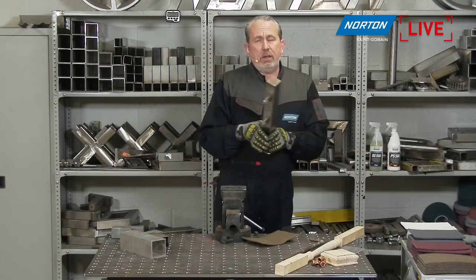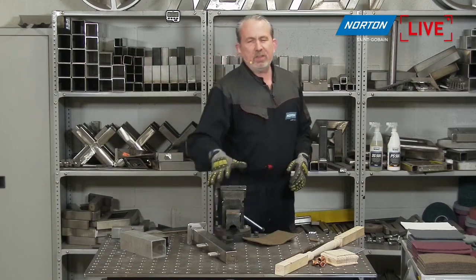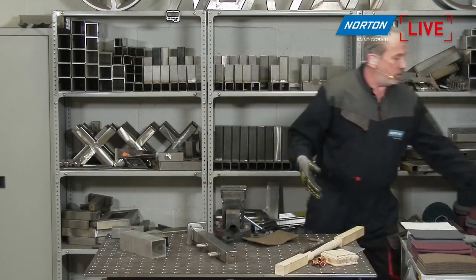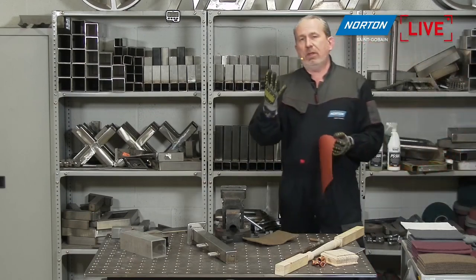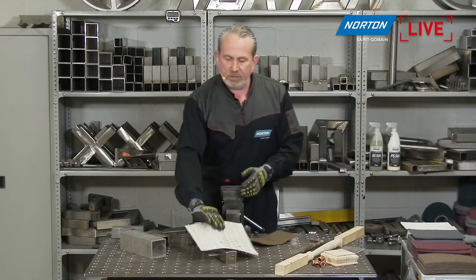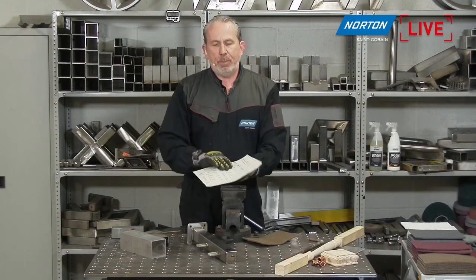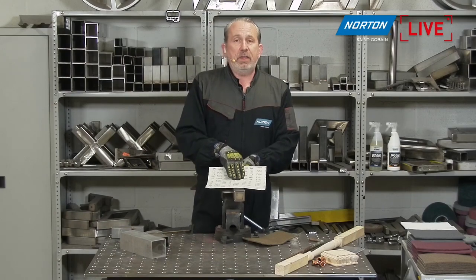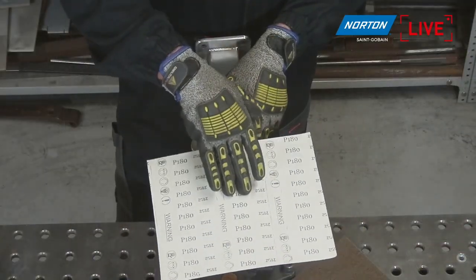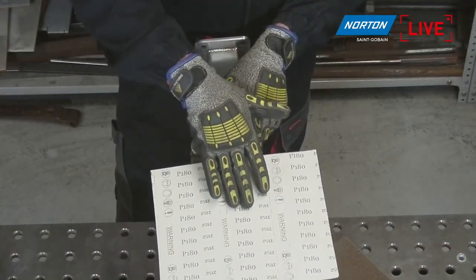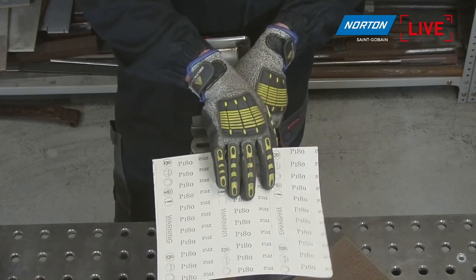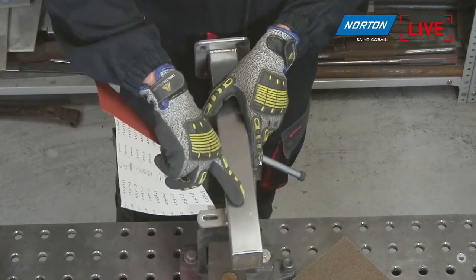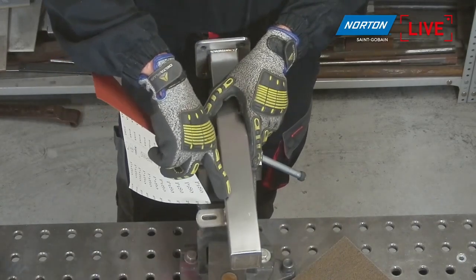Another thing where hand pads benefit on more aggressive applications like this is when you're using sandpaper, you're pushing on it with your fingers into something like here. So you actually get more pressure into where you're sanding with where your fingers are touching. You'll actually see that in the surface finish that you get with these two fingers when you're trying to sand on there. You'll see more aggression on the material, almost a witness mark where your hands have been.